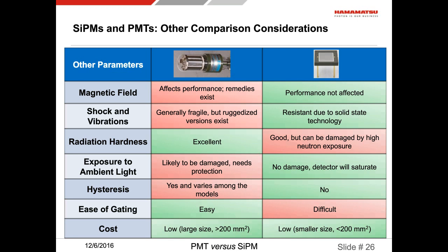Hysteresis, yes, for PMTs. Hysteresis refers to a situation where current operation of a device depends on its history of operation. It's kind of like a memory of what happened in the past. So yes, PMTs do have hysteresis to various degrees. SiPMs, none. Ease of gating, easy for PMTs, rather difficult for SiPMs.